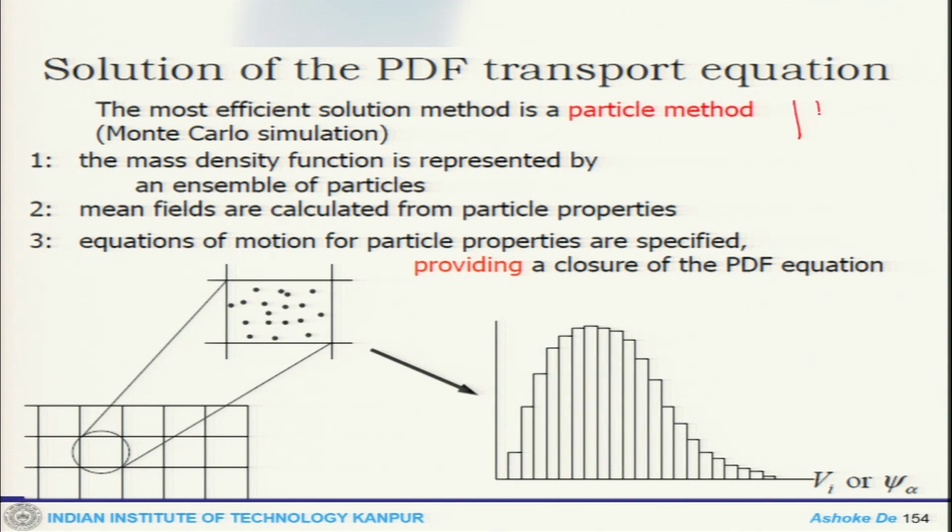So, you need a hybrid approach, that means you will solve some of the mean quantities in the Eulerian framework, then in each computational cell you have some n number of particles. These particles have some mass, they are not massless particles, and they are also exposed to reaction, mixing and the turbulent fluctuation. They will change their position randomly, and be affected by mixing, reaction and diffusion. Finally, there is a conservation of the global mass for each computational cell, and the information is passed back to the Eulerian framework. So, there is a handshaking required between your two frameworks, the Eulerian and the Lagrangian.